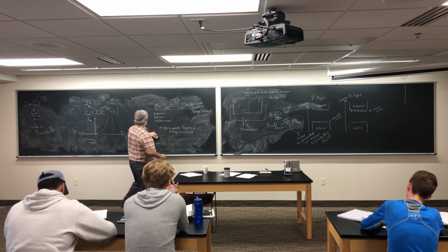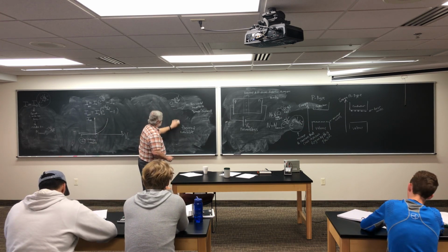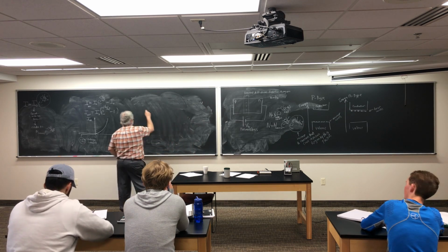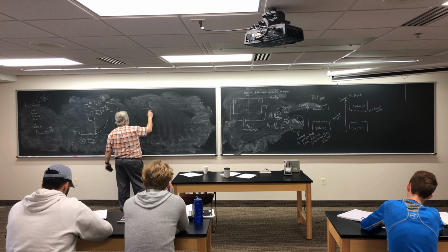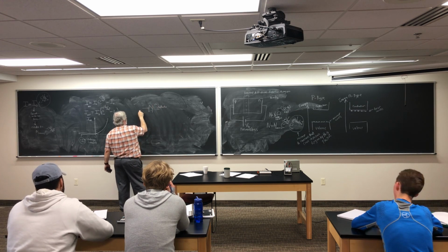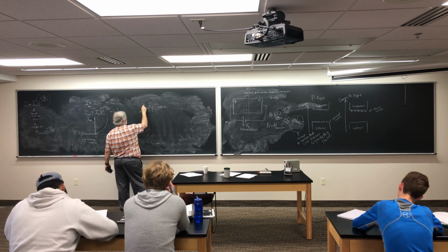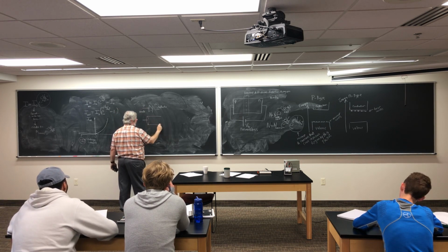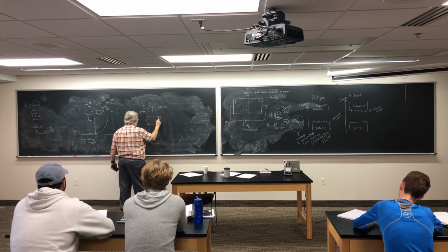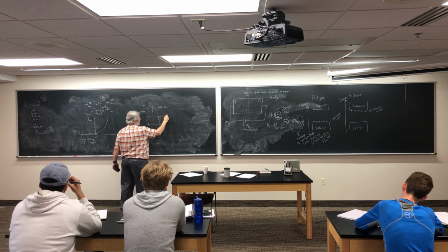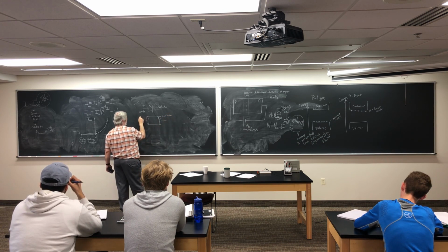So that's the basics of the PN junction diode. And if you remember, I told you the symbol for it is this. This is the cathode side, meaning that's the N type. This is the anode. This is the P type. And if you actually have a cylindrical one like I showed you the other day, there's usually a little band here that tells you which side is the cathode and which side is the anode.